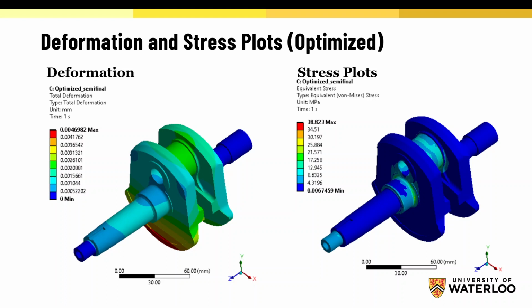Excellent point. So they did do that. I didn't put the slides in here. That's often one thing that people overlook when you remove mass from something. Not only are you changing the polar moment of inertia, you're changing the center of mass, and often components that rotate are balanced to a certain geometric property because their center of mass is in a certain location. So often when you remove a bunch of mass, it screws all of that up. So yes, they did do that.